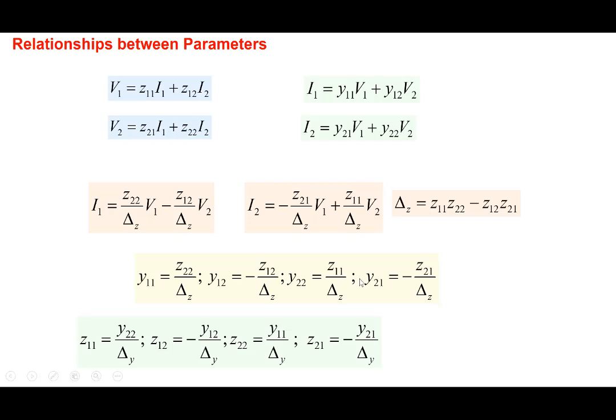And of course, vice versa also I can do. Suppose you have taken a circuit, experimentally measured or analyzed and determined Y11 and all these Y parameters that are there. And for some reason you are interested in Z parameters, well, you can obtain Z parameters also, right? And of course it would be obvious that you can determine the H parameters and the G parameters also from the one single set of measurements here. A few more things and then we'll wind up our discussion.